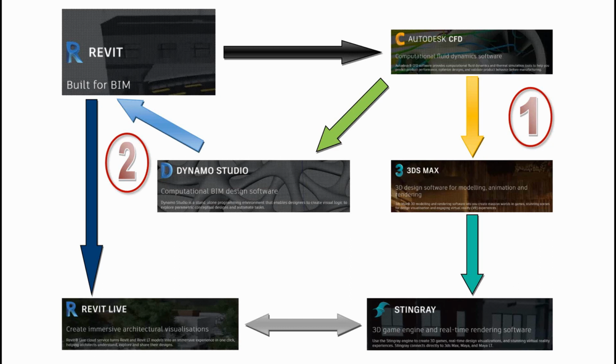But some clever guys came up with Dynamo. In CFD, we can export our nodal results and bring the results back into Revit, because with Dynamo I can produce a script which reads the data from CFD and creates some families. I want to demonstrate this later with a couple of examples of a data set with 820,000 nodes, which works well, where we can bring the whole data back into Revit.